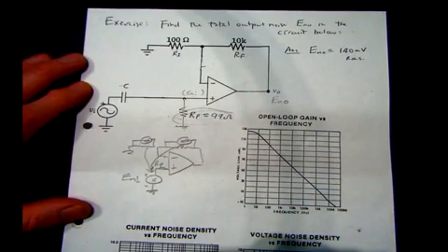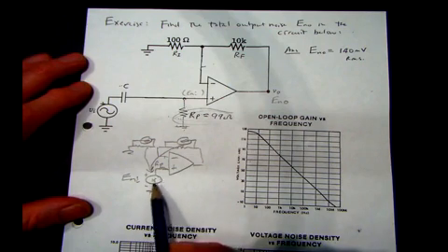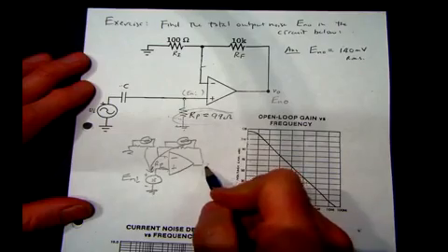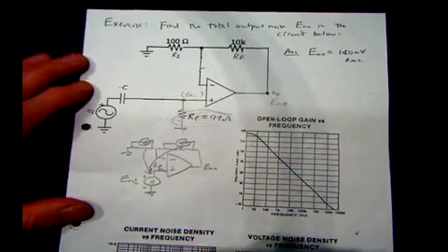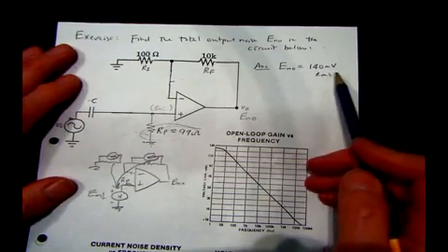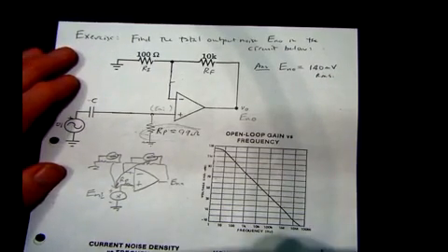And that's why sometimes you hear the non-inverting gain of an op-amp stage being referred to as the noise gain. So when you accumulate all those noise sources at input and then amplify it, we end up with an output noise. And as I said, I calculated that way back to be 140 millivolts.